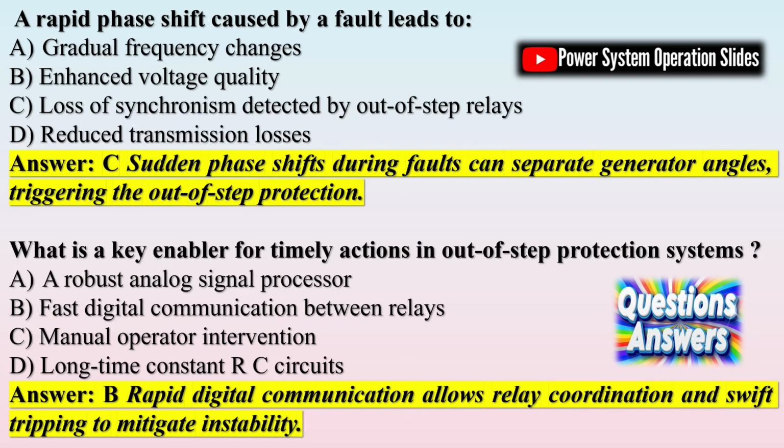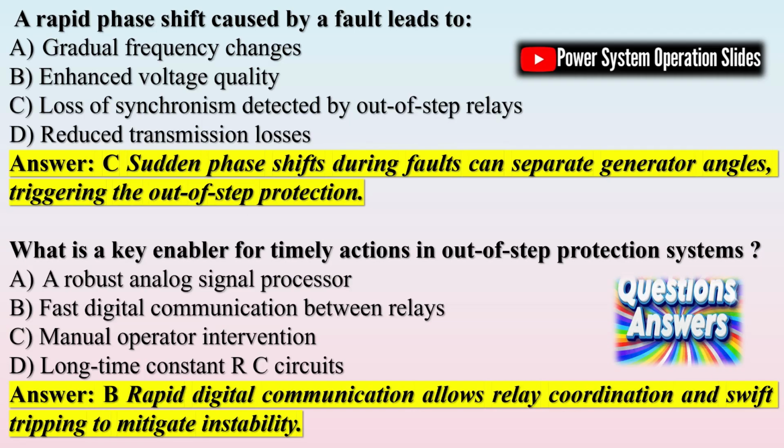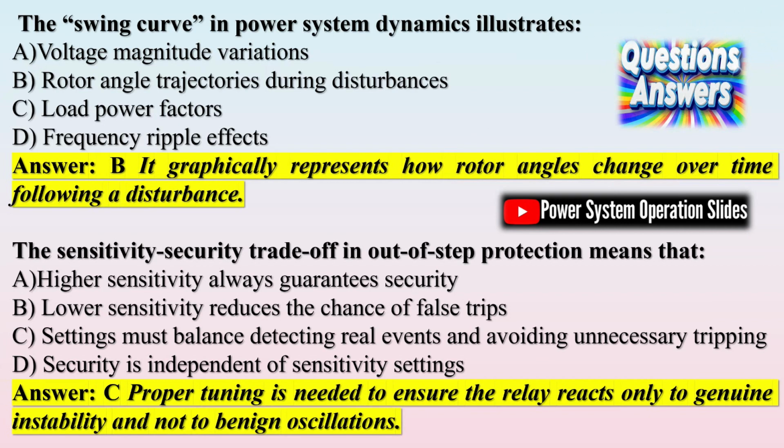Implementing out-of-step and out-of-step blocking functions in a large power system is challenging due to the inherent complexity and varying operating conditions. Although the basic philosophy is simple, selecting optimal network locations for these systems requires extensive transient stability studies. These studies reveal constraints on angular stability, identify generators prone to losing synchronism, and map out the swing loci, that is, the paths of voltage and current variations during disturbances.